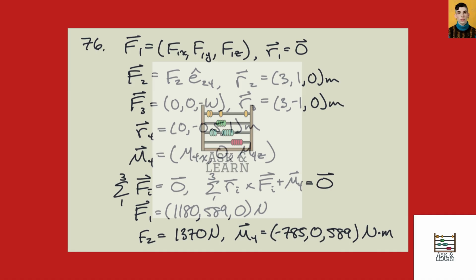So in this problem, we have a T-bar extending from a rod, and at the support where it's attached to the wall, it's supported in all the directions. So we have force components in all three directions at that point, and that is what we're using as our origin. There is a rope attached to one of the sides of the T and a weight attached to the other. So that rope goes from point 2 to point 4 and has a magnitude of F2, so in this direction.